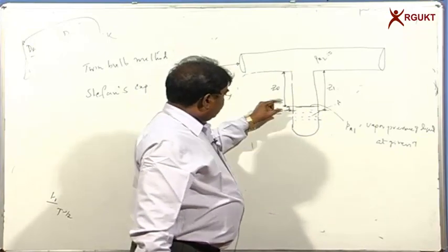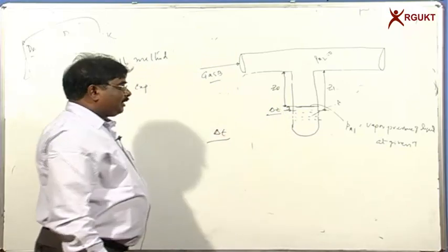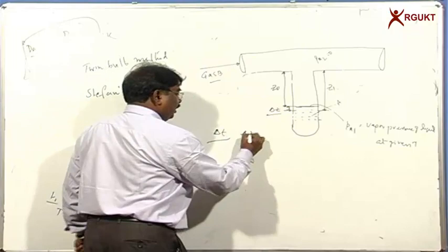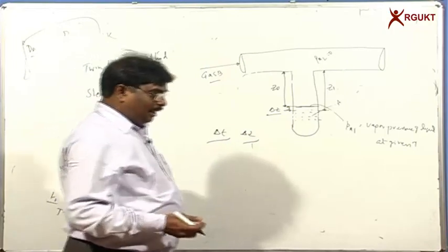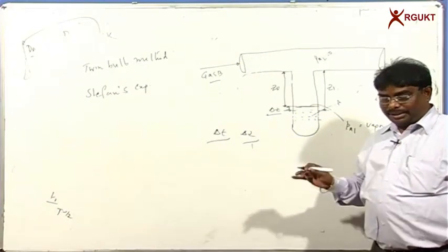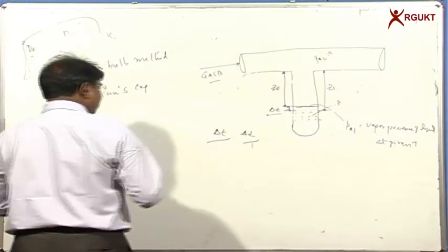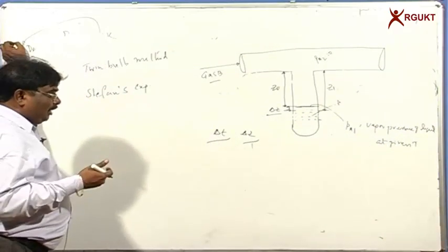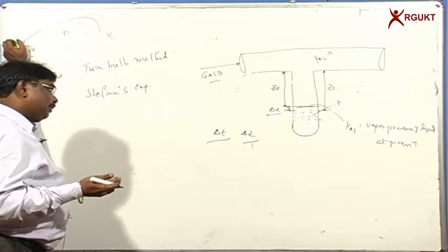In a given delta T time, the liquid depth falls by delta Z, and the system again comes to a new steady state. We don't really call it a new steady state, we call it a pseudo steady state approximation. Because the rate of evaporation of the liquid is very, very small, we can assume that pseudo steady state evaporation is achieved.